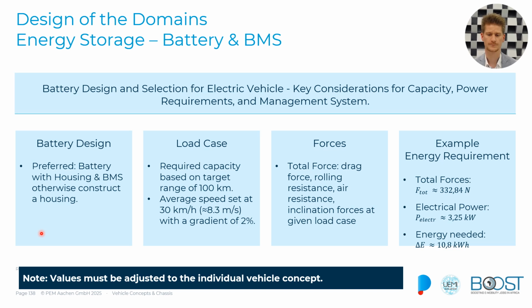So again, we have our total forces regarding the drag force, the rolling resistance, air resistance, inclination forces, and the given load cases, and we then can start to calculate what might be necessary regarding the total force, which we have over here. Then we create the amount of electrical power that we would need, and then with the efficiency grades and the time of use, we can end up with the energy needed, and this would then be the energy, or the capacity, that we at least need to have in our battery.